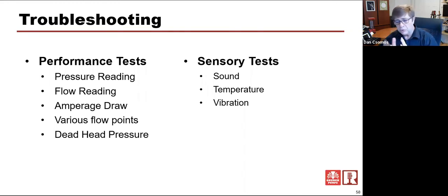The other troubleshooting senses that you have, to be able to judge flow rate, about the only way is an ultrasonic meter or some kind of flow meter in a system, or maybe a bucket test if it's a low enough flow rate, where you actually measure how much flow is coming out of a system in a bucket and time it. But the other things that you have are sensory tests.